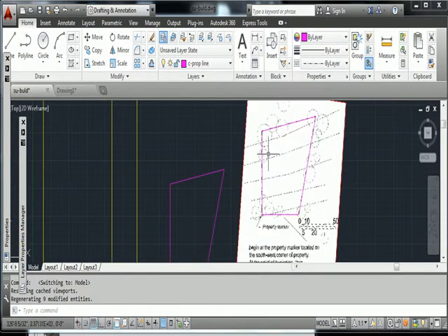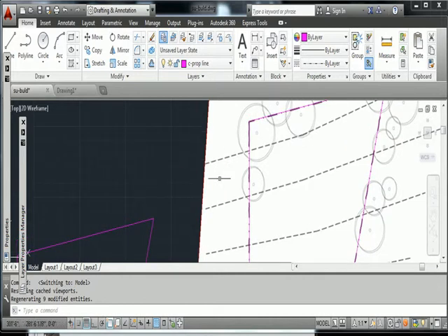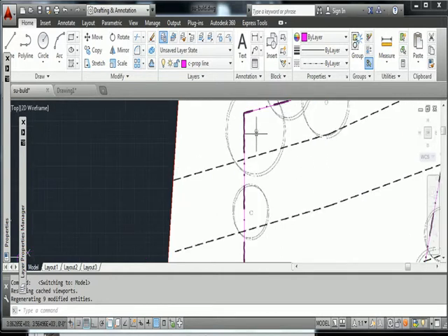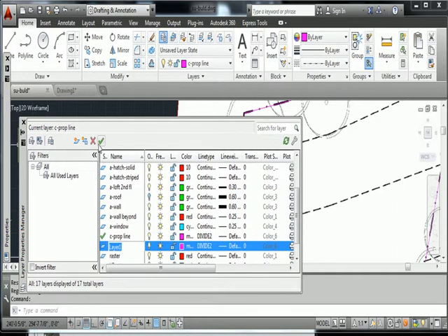What I want us to do right now is to go back to your model space and trace where there are trees. That's the trunk. Those are the canopy line, and I would like you to trace the contour lines. Okay, notice that the contour lines are probably in the hidden line and the tree is in the solid line, but they'll both be on different layers. So you might want to select the, did we make those layers? No, I guess we didn't, huh? So we might want to create a new layer, C-topo for topography.